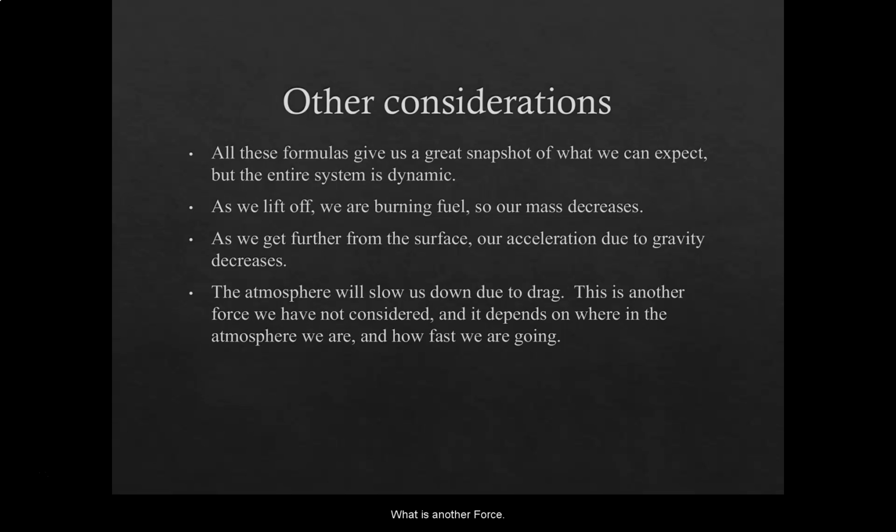That is another force we have not yet considered, and how much it will slow you down will depend on a number of factors, but most especially, it depends on where you are in the atmosphere. The lower you are, the thicker and denser the air will be, and hence the more effect the air drag will have. It also depends on how fast you are going. When you're moving slowly, air drag is not that major an effect. But as you speed up, it becomes quite important in the overall dynamics of the rocket launch. But at the same time, the faster you're going, the higher up you are, the thinner the air gets. So there are competing factors to take into account there.